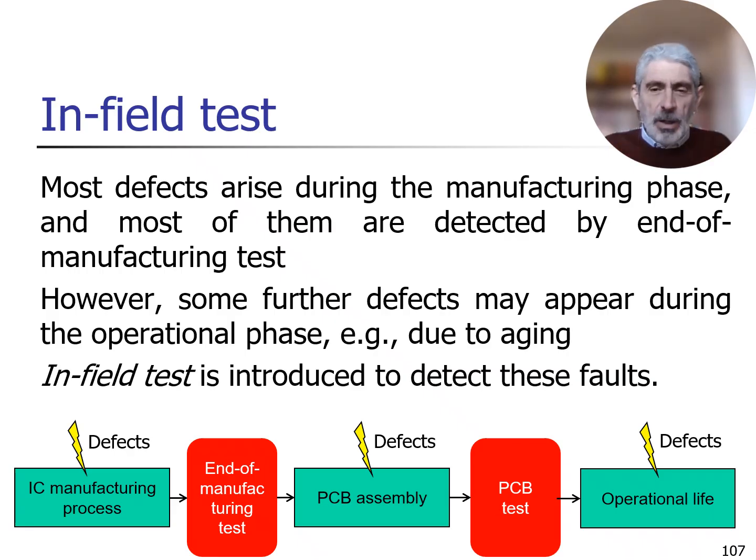Then, even if the board is perfectly fault-free, it is mounted on the system, and everything works perfectly at the beginning of the operational phase, it may be that during the operational phase, some defects arise. Why? For example, due to aging. New semiconductor technologies are more prone to aging than the old and more mature ones. So we need to perform periodically some in-field test in order to detect these faults that arose or are arising in the circuit during the operational phase.